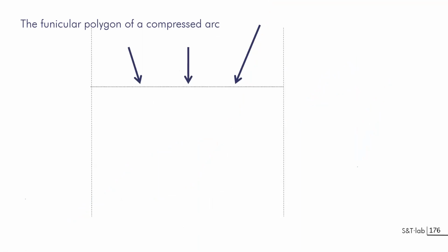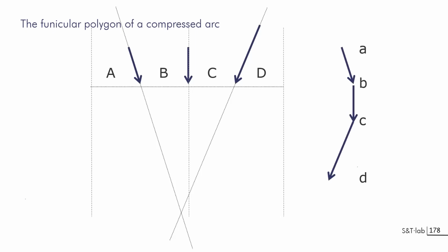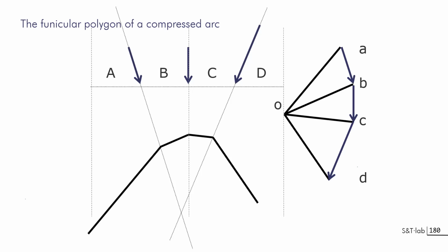And what about non-vertical forces? As you can see here, these forces are not fully equilibrated, and so you have movement on one side of the system. And this construction of the funicular polygon will help you to define this. So let's construct the load line that is not rectilinear. This is curved. In this case, let's get a pole and get the rays. Let's get the funicular polygon, and let's get the resultant. You have the resultant by lengthening the side system.